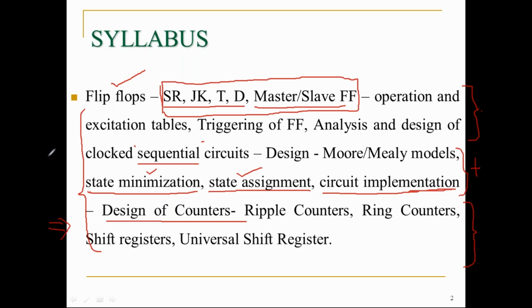For that you should know some basic steps. We have to draw the logical diagram or a truth table, like in a combinational circuit, here also. So: truth table, state assignment, state table, and then logical circuit implementation. That's all. Now I am entering into the subject.